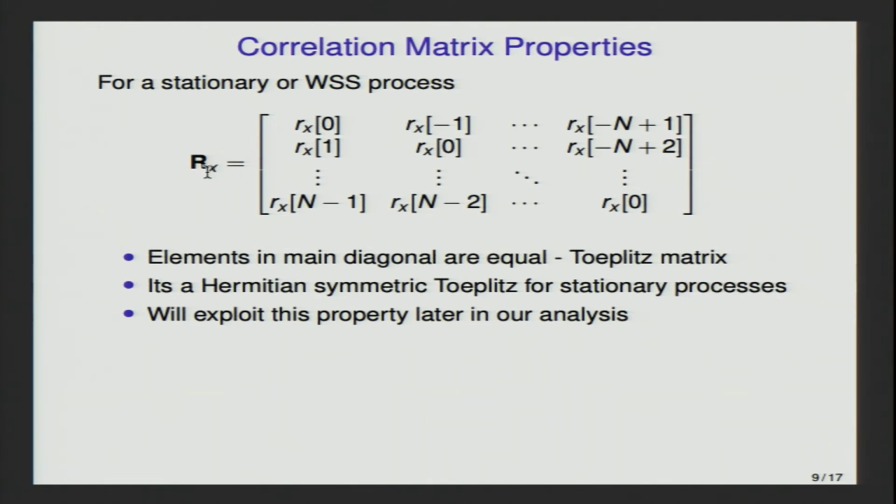When we revisit this in terms of implementation, I will mention it at that point, but for now it is sufficient to know that this autocorrelation matrix typically has good properties. An additional property: we saw previously that Rx0 is the largest among them and it is going to be positive. So, we will also see that this autocorrelation matrix will be a positive definite matrix. These are some properties of the autocorrelation matrix which will be useful later when we come back to use them.